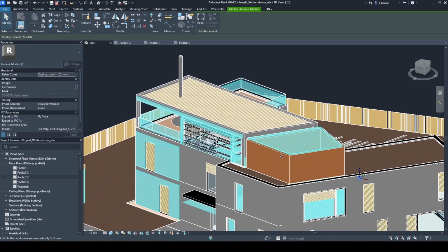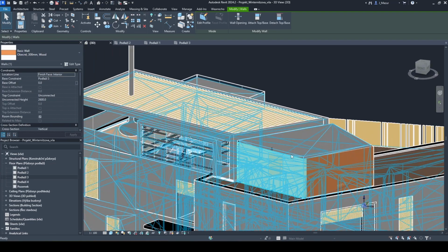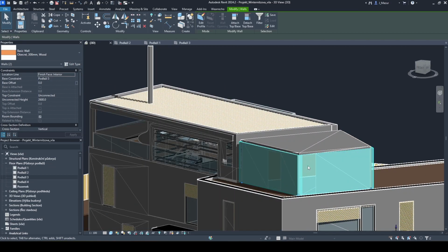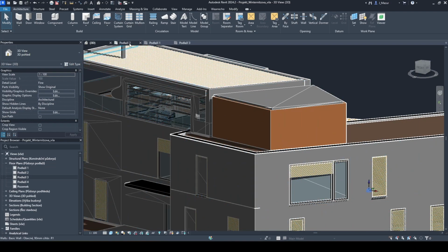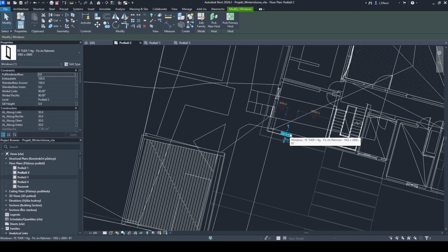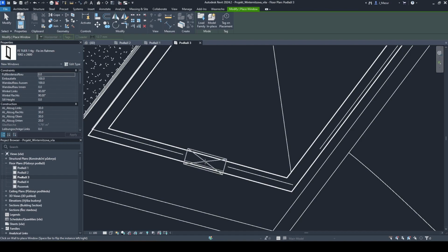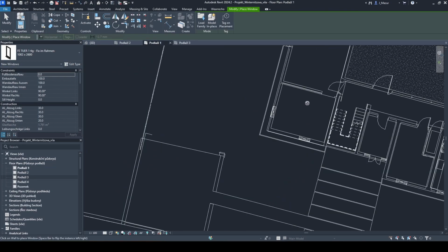Perfect. Let's take these walls, let's select, and you can see windows behind them, right? Because I created openings there. There's one on the left, and they're small windows. So what I would do is go to this floor, select this window because we already have them, and when I zoom you can see where they are, so you can place them in the right position. It's Revit, so you can make them precisely where you want them to the millimeter, but in VR we made it like a 3D sketch.